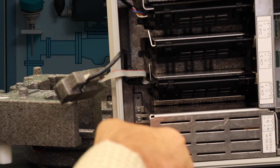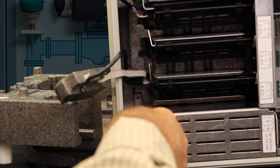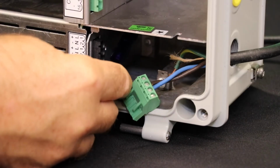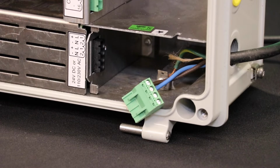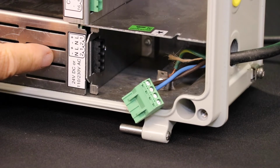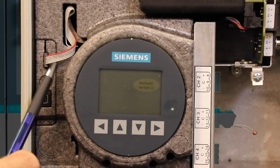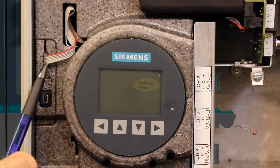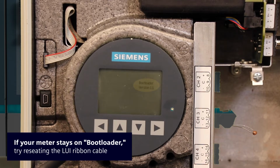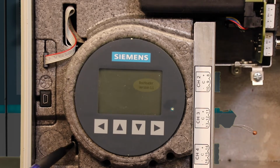If you ever need to replace the power supply, it is held on by 3 screws. There are 2 here, and there's one all the way in the back here. Once those screws are loosened and removed, this power supply will pop right out. So you should make sure that this connector is plugged in good. And as you recall, the other end of this piece is another short cable that goes into the top of the transmitter cassette. And you want to make sure that that end is plugged in correctly as well.